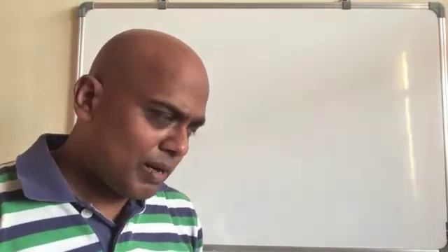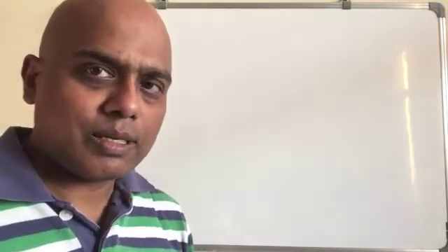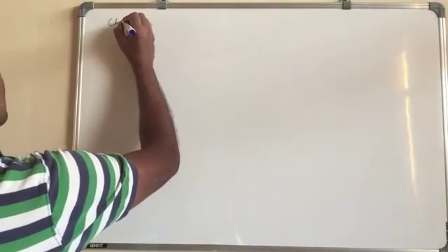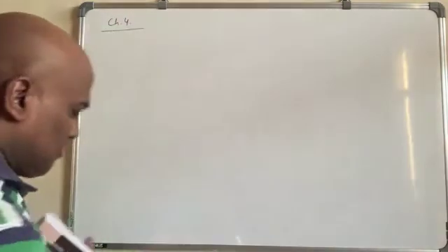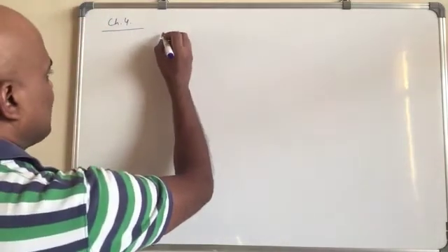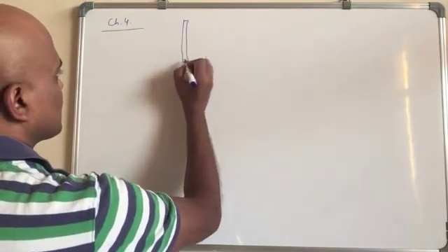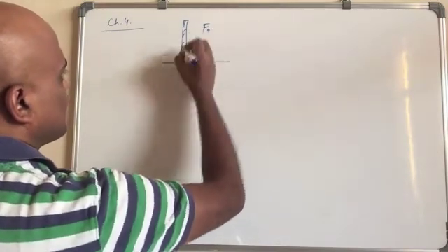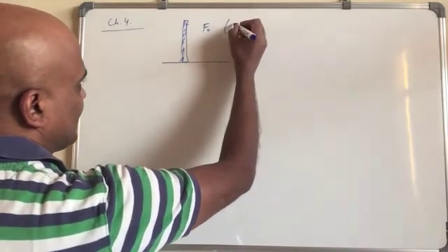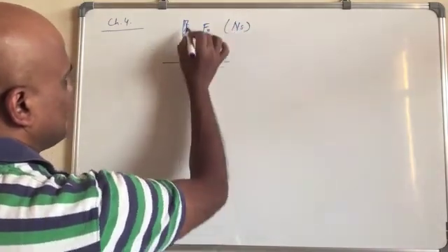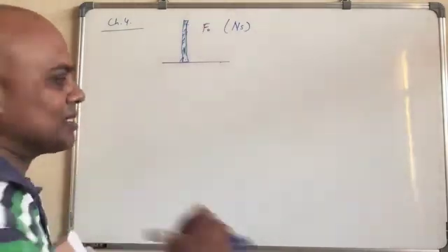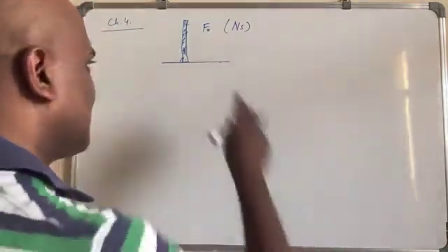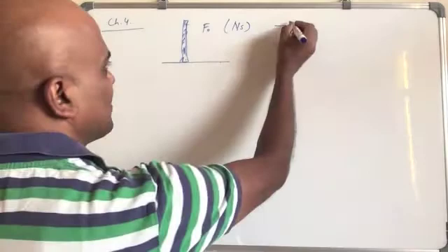So we are done with chapters 5 and 6 on multi degree of freedom. From chapter 4, transient vibration, one problem was given the impulse. The impulse F naught is the actual area of that; it is given in Newton-seconds. This is a short impulse, and I'm asking what is the velocity immediately after the application of the impulse for the spring mass system, right?